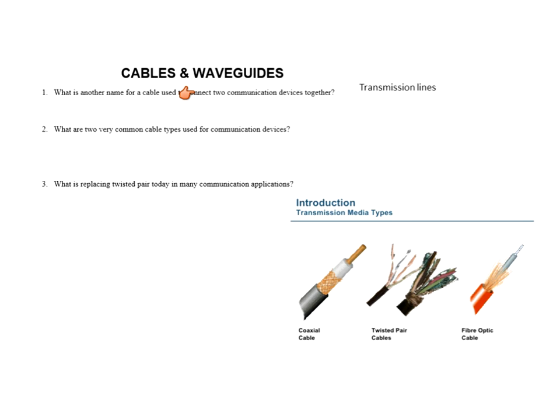Now, what are two very common cable types that are used as transmission lines? Well, there's two really popular kinds. Although there's about 5 or 6 of them, the ones that you'll be tested on will be the coaxial cable and the twisted pair. In serial communication, you always run into the twisted pair. Coaxial cable is typically in RF, testing RF. For example, your BNC to alligator cable in your kit or your oscilloscope probe is a type of coaxial cable.